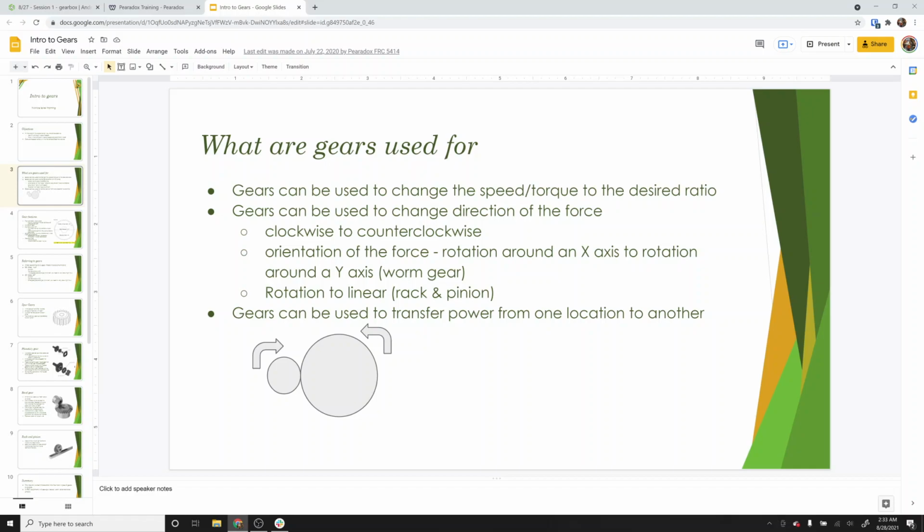So if we have a gear on a motor that is 1/3 of the size of an output gear, what ends up happening is that if we want this one to turn 1 time, this one has to turn 3 times. And so this ends up going much slower, but it also has more torque, which is something we'll talk about at a later date. So we use gear ratios to either change the speed or change the torque available.